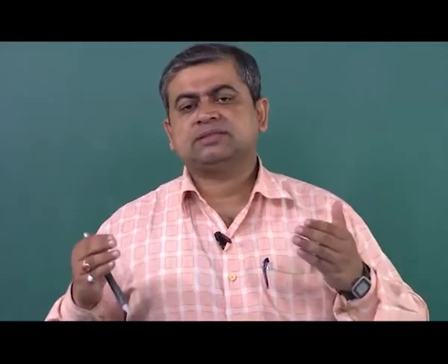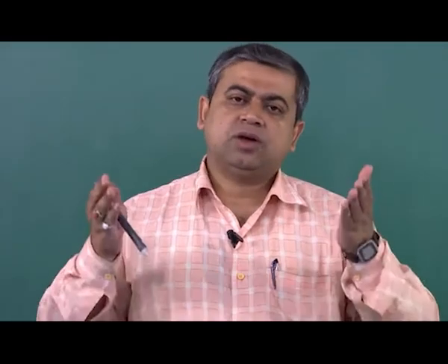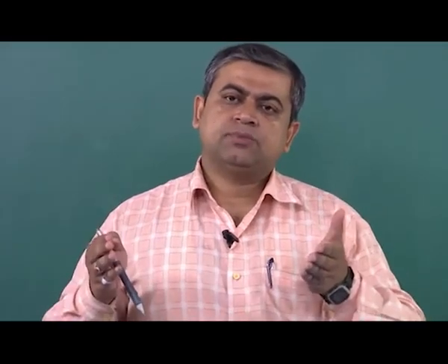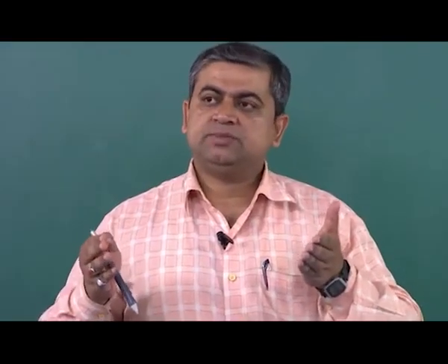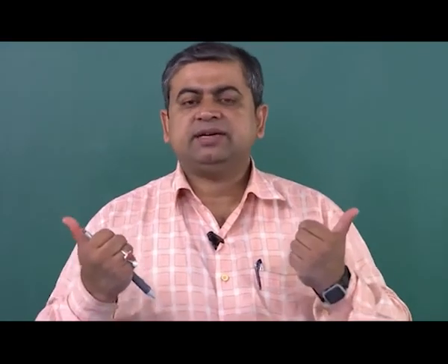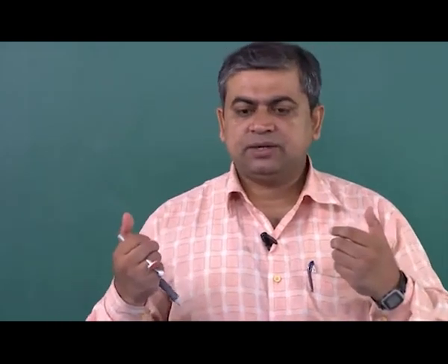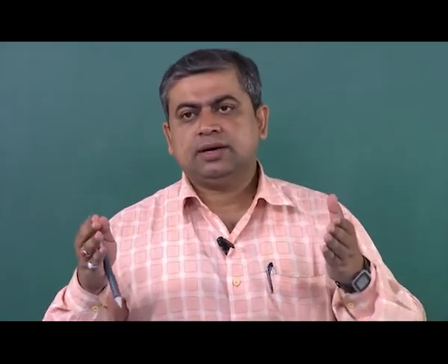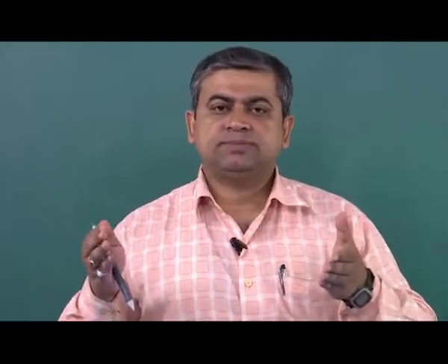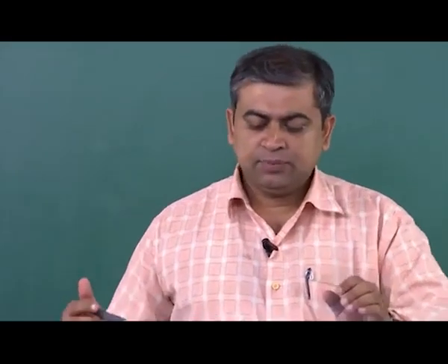Therefore, as long as the drilling process is continuing and the material comes off from this cavity which is being formed, the sides of the cavity are also equally exposed, and that results in some continuous removal on the sides, and they are more exposed in comparison to the very bottom, and so therefore the slight taper.